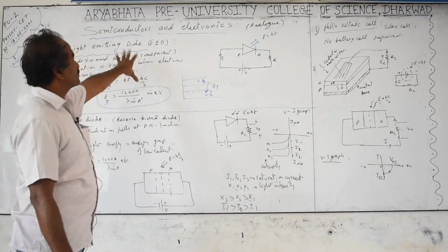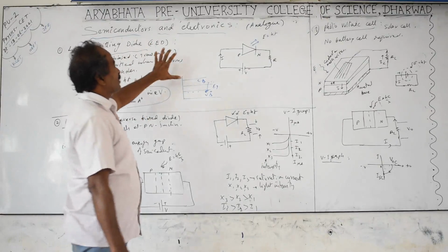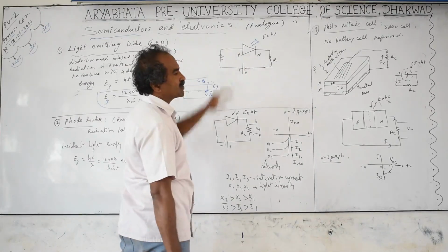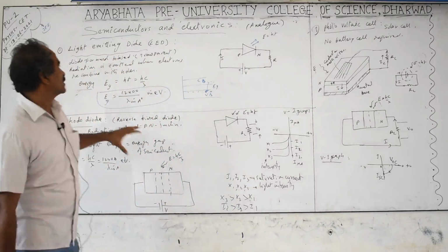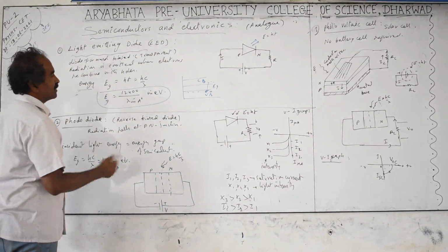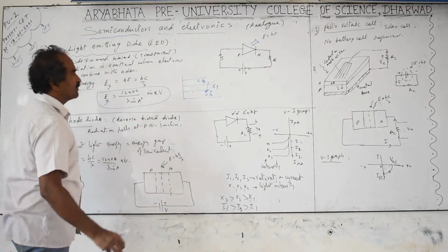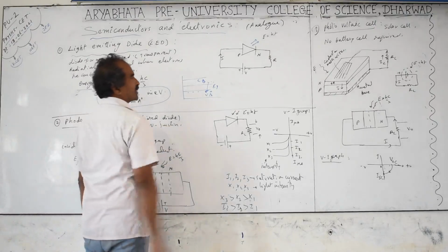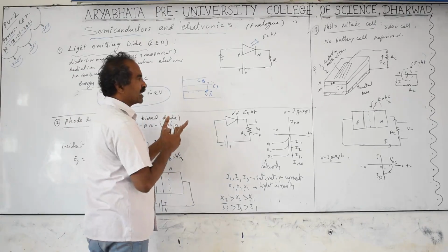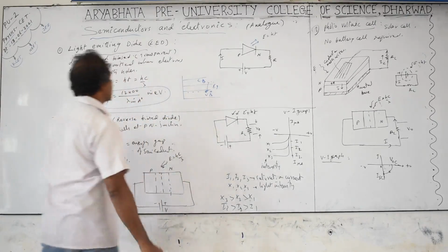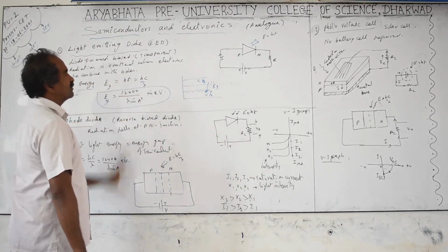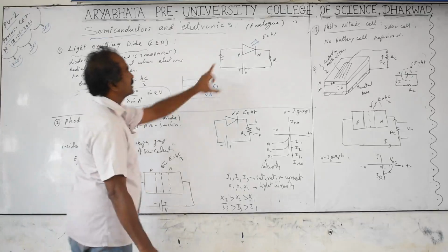And the LED lifetime is practically permanent, infinite. But the problem with this LED is that it won't produce all possible wavelengths. Even if it produces white light, it does not produce all possible wavelengths. Different colors depend on different energy gaps. Different energy gaps can be made by adding different impurities, which change the energy gap of the semiconductors. Generally 4th group elements, 3rd group elements and 5th group elements are mixed together to produce different wavelengths. You will not get a continuous spectrum from the light of these LEDs.